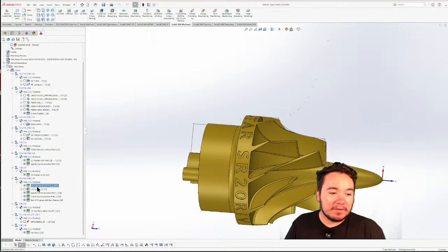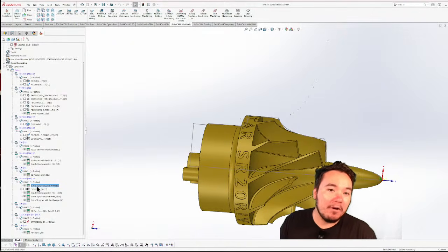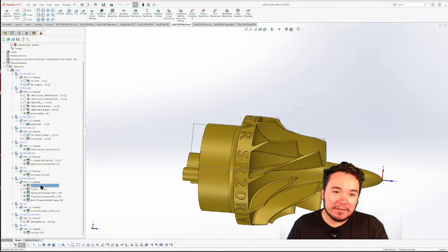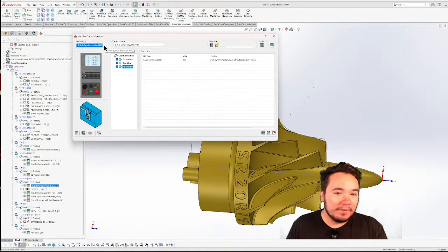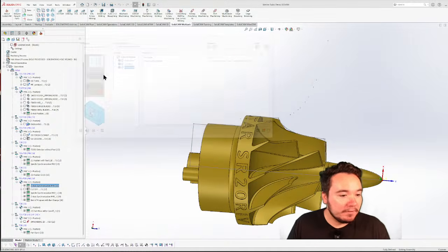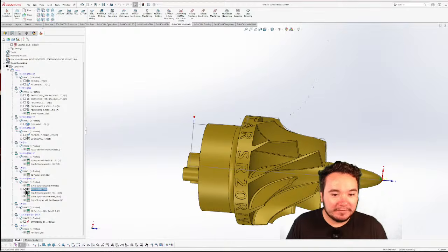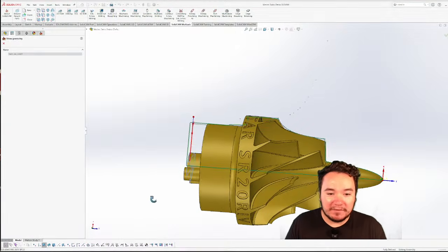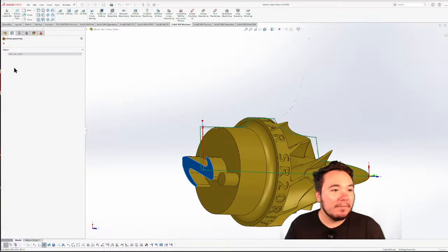And then you have Z-axis synchronization after you're clamped on to the part, because now you have sub and main both clamped. So you want to synchronize the Z-axis after you do the end position pickup on the sub spindle. And again, that's just a simple save and copy from the last MCO I selected, and go to technology and change it from there. All right, and then we can just do our cutoff, just a simple plain cutoff operation. Selecting the geometry, I just selected the face twice to get that little line to come down.